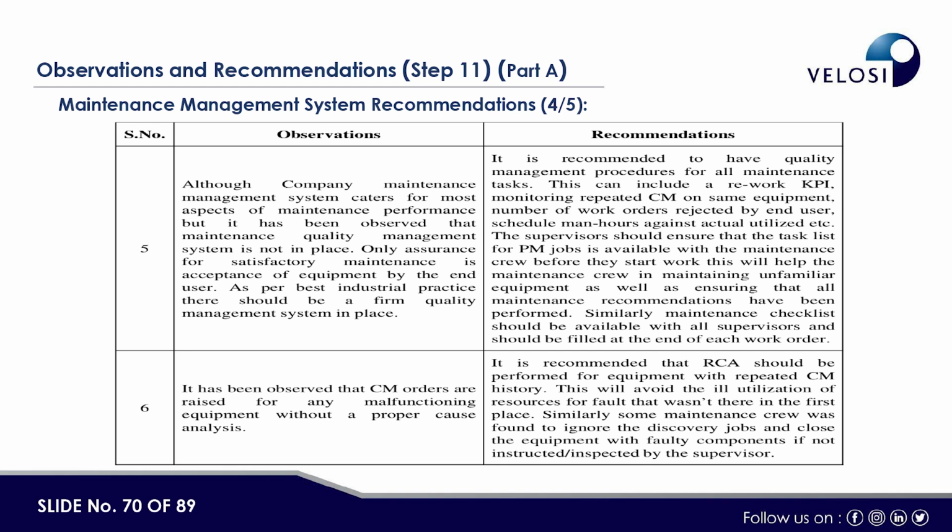It has been observed that CM orders are raised for any malfunctioning equipment without a proper root cause analysis. So efficiency could also improve if some root cause analysis could be done, so that reoccurrence of the same failure could be avoided.